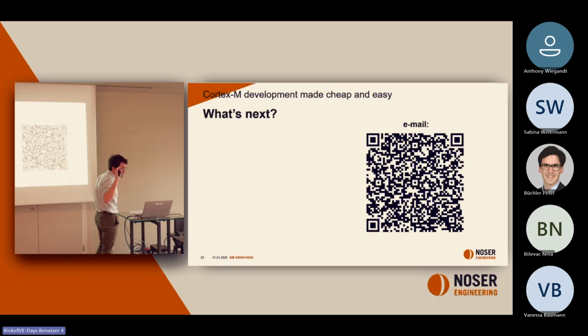I made 4 examples of projects with a single CMakeLists file, showing how to integrate the ThreadX real-time OS and how to integrate the different source code from STM32Cube, so from the STM32 HAL, the hardware abstraction layer.